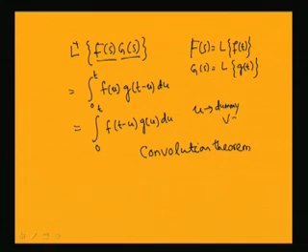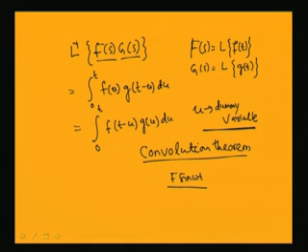This convolution theorem is an important theorem which you can apply for finding the steady state response of a system. When you know the forcing function, say a force F sin omega t acts on a system and you know the Laplace transform of this and you want to find the response, you can use this convolution theorem to find the response.